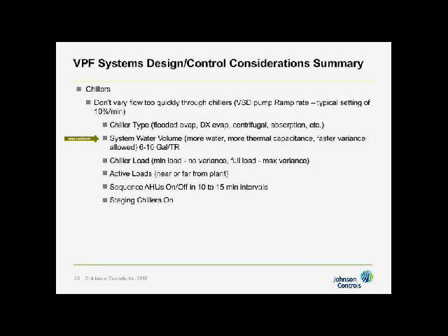Another way that I like to explain this particular phenomenon is when a gallon of water leaves the chiller and goes out to the system, breaks up and goes around to everything, and then reassembles in the return and returns back to the chiller, the longer the amount of time that takes to leave the chiller and return, the faster the chiller can handle the rate of change. Okay?